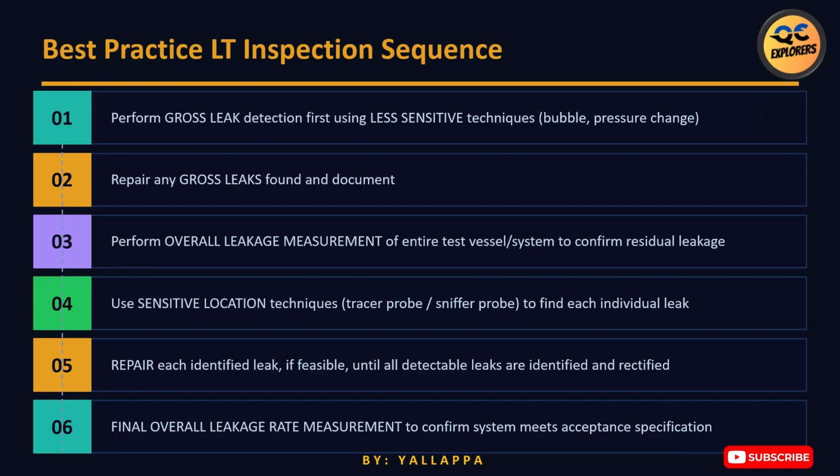Common interview question. Why should gross leaks be repaired before performing highly sensitive leak testing? Because large leaks can interfere with sensitive measurements and waste inspection time. Level 3 Exam Trap.